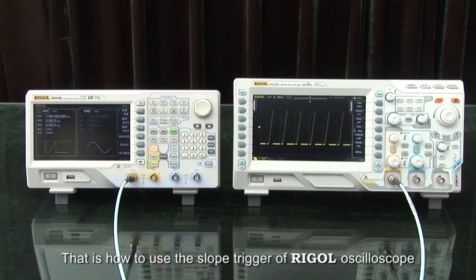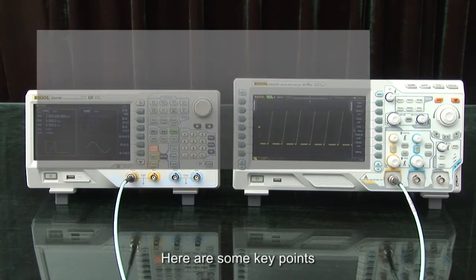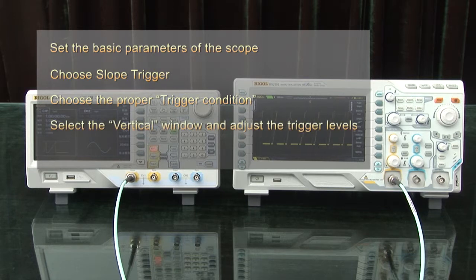That's how the slope trigger for the Rigol oscilloscopes is configured. Here's a summary of the key points. You want to set the basic parameters of the scope, choose the slope trigger, choose the proper trigger condition, select the vertical window and adjust the trigger levels, and then set the proper time frame.